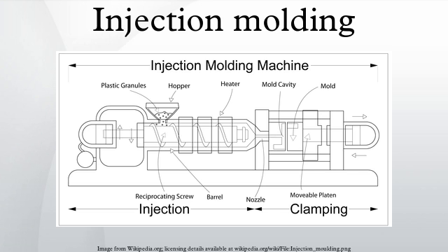This typically means that the residence time and temperature of the chemical precursors are minimized in the injection unit. The residence time can be reduced by minimizing the barrel's volume capacity and by maximizing the cycle times. These factors have led to the use of a thermally isolated, cold injection unit that injects the reacting chemicals into a thermally isolated hot mold, which increases the rate of chemical reactions and results in shorter time required to achieve a solidified thermoset component. After the part has solidified, valves close to isolate the injection system and chemical precursors, and the mold opens to eject the molded parts. Then, the mold closes and the process repeats.